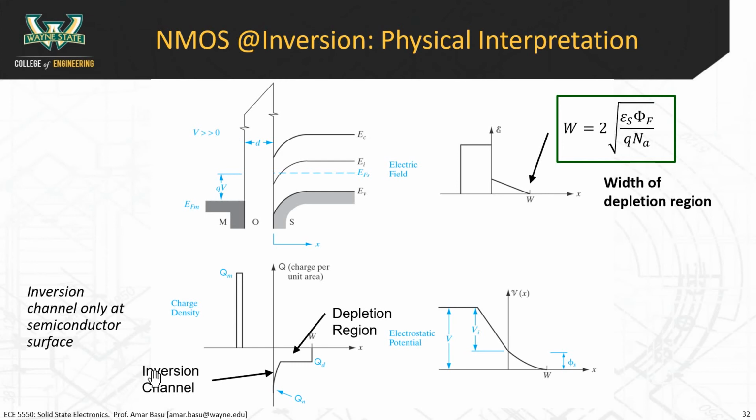So if you remember what we did in the diode chapter, the electric field at some point x, we have to take the integral of charge, everything to the left of that point. So imagine our x moving in this direction.